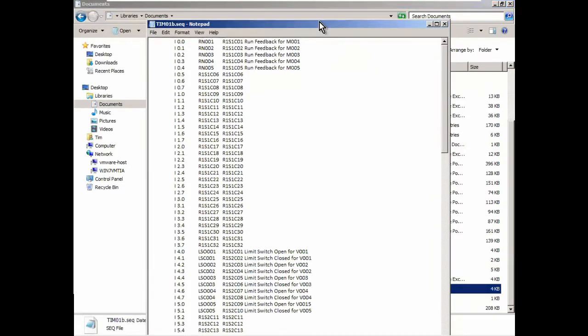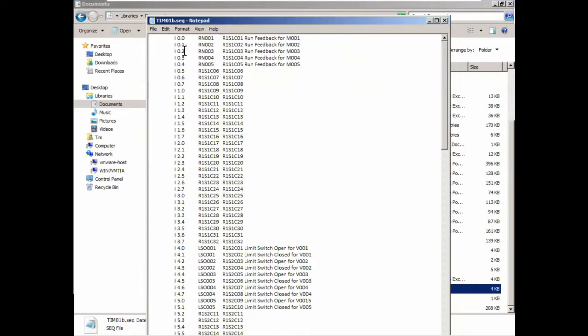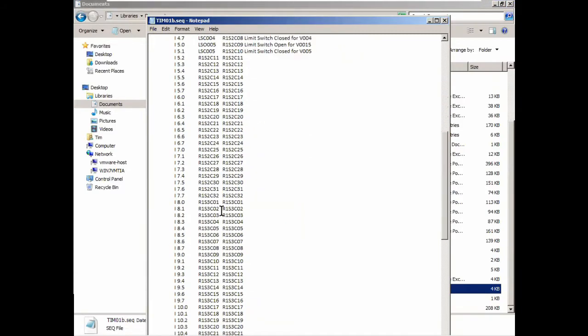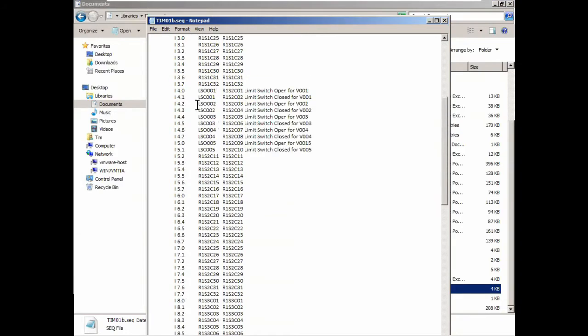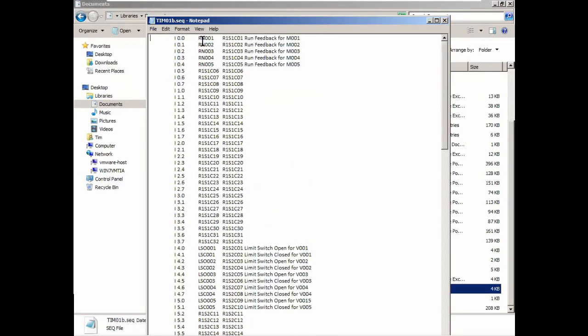So I've created all the I/O for our little incredible machine, and you see I've labeled the I/O, and there's the rack 1, slot 1, channel 1 in the comment. And then these are the spares, so the symbol is the same. So if you ever use this, straight away you'll know this one wasn't configured before, so I'm just going to put a symbol on it and give it a comment.